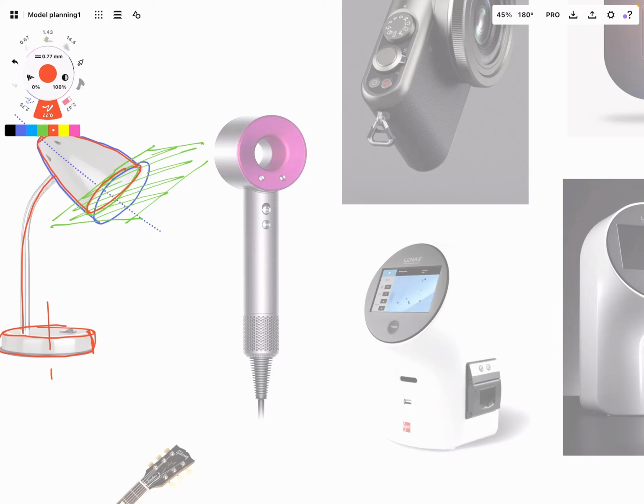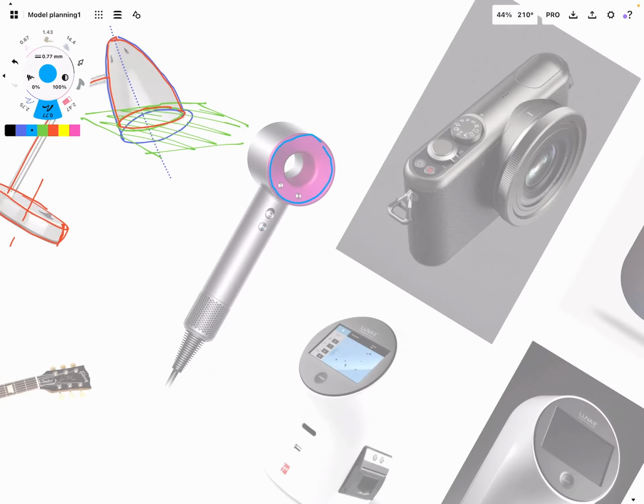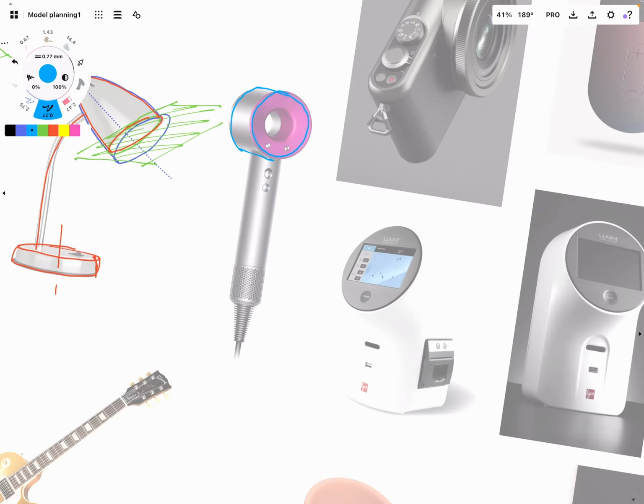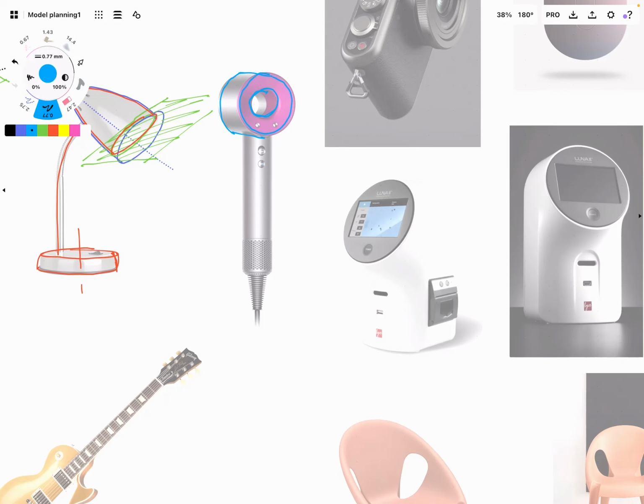So we have a cylinder. So you could do an extrude, like so, cut a hole through the middle, and then you end up with the resultant line around here, where the two parts intersect, where the second cylinder comes in and intersects. So again, this looks like a revolve, and then some fun on the strain relief down here.